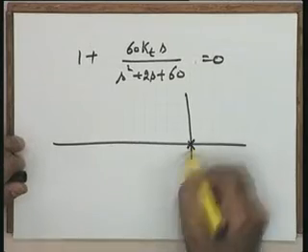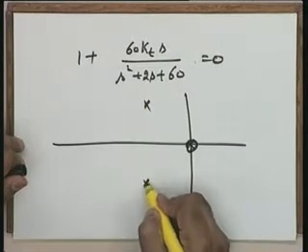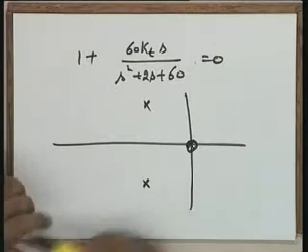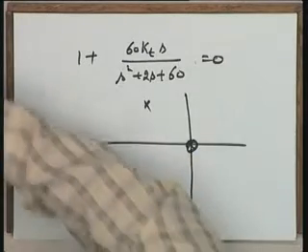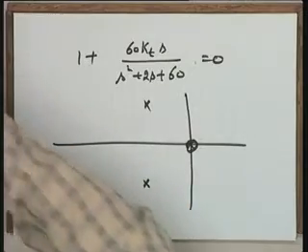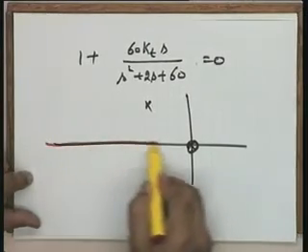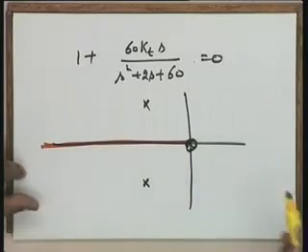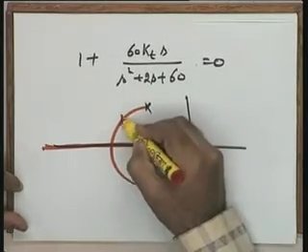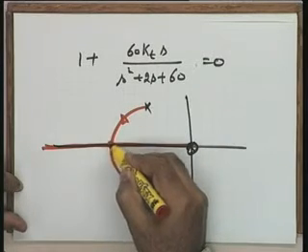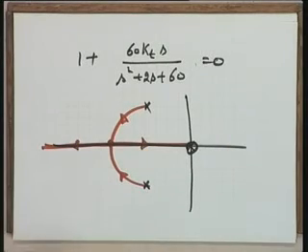So in this particular case you find a zero at this particular point, and there are two complex conjugate poles. Now I leave this as a simple exercise to you. If I have the values in my notes I will give you, otherwise the general sketch. Let me give you the general sketch. This is on the root locus. The root locus in this particular case is going like this. Here is the breakaway point. These are the two root locus branches.